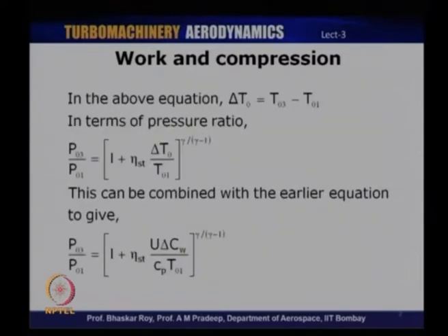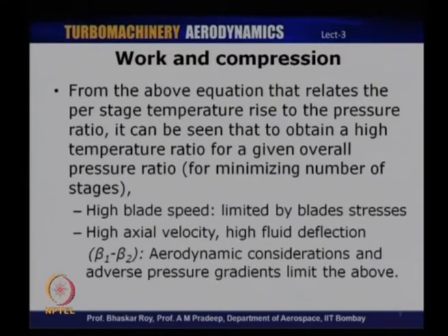But of course, one can see from this pressure ratio relation with the temperature rise or the blade speed, one can at least estimate the parameters on which an increase in pressure ratio can be achieved. So, what we have discussed now is, from simple thermodynamics, how we can estimate the pressure ratio that one can achieve per stage using parameters like the temperature and the inlet conditions, as well as some of the parameters coming from the velocity triangles.